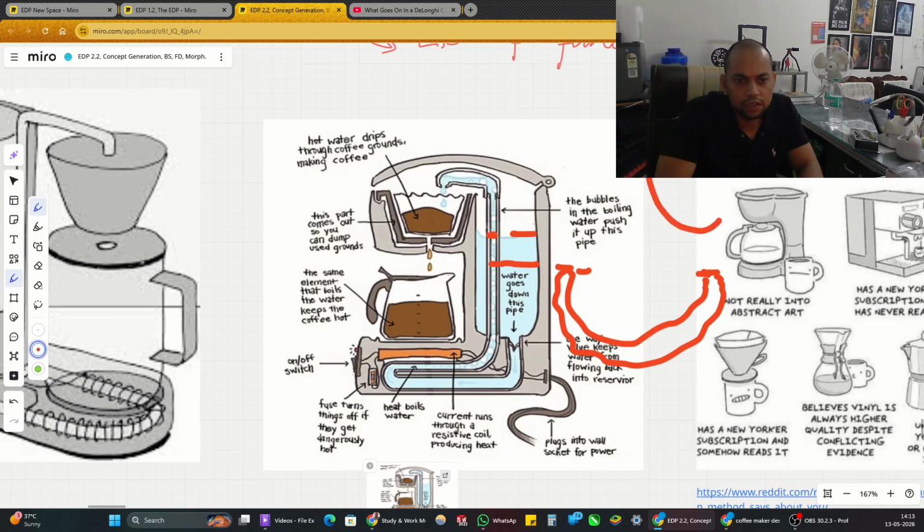If you fill water in a tube, because both of these ends are exposed to atmosphere, equal pressure is being applied at both of the ends, and because of this both the levels are going to be the same. This is called a water level and is used in many engineering applications.